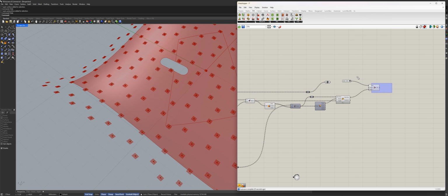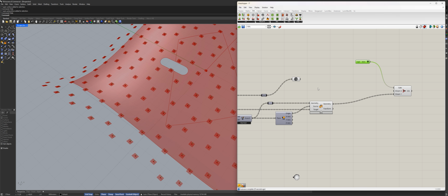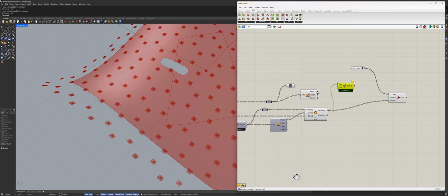Go here. Okay, so I will use the node called statistics, take the paths. This is my paths. Now I will use the tree branch as well, as we did before, multiple times already. Tree branch, we'll take our geometry and our paths and plug that in right there.